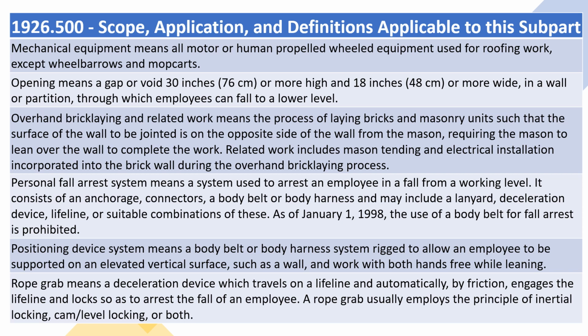Rope grab means a deceleration device which travels on a lifeline and automatically, by friction, engages the lifeline and locks so as to arrest the fall of an employee. A rope grab usually employs the principle of inertial locking, cam/level locking, or both.